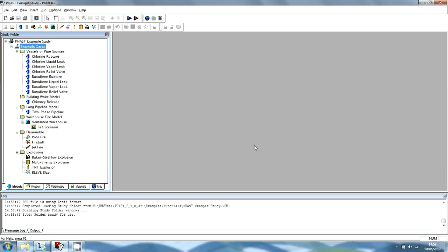The appearance of the main window changes when the study folder is open. There are many more toolbars and there is a pane with 5 tab sections at the left hand side of the window. The pane is known as the study tree pane, and you work in its various tab sections to set up the input data for the analysis.